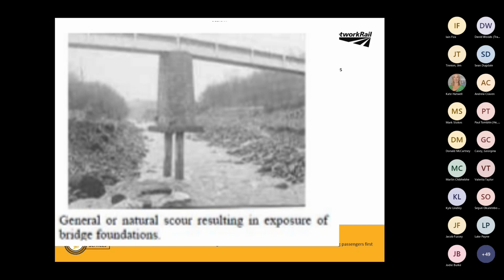That picture there looks ancient. It actually wasn't. It was taken by Jeremy Benn back in, I believe, about 1998. And the Environment Agency declared that structure was safe. Now, what you can see here is a riverbed level originally. We've got a really deep depression, a scour hole. These are the piles, which are the foundation. There's the foundation cap, and that's the pier of that bridge.